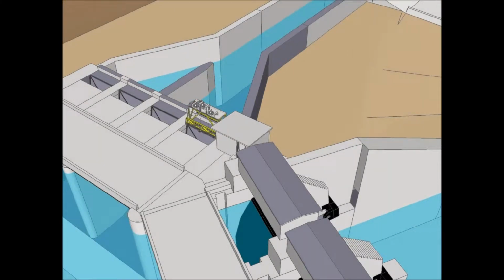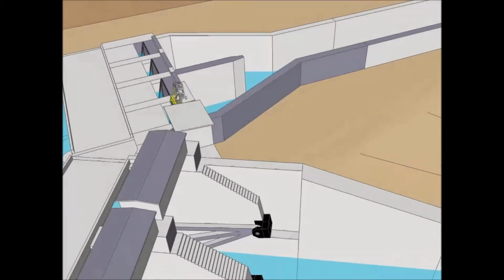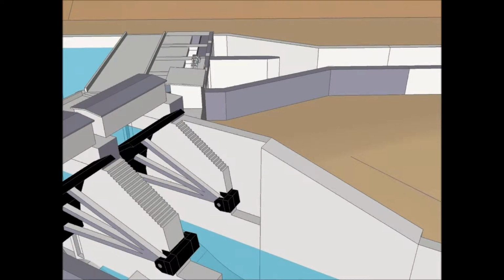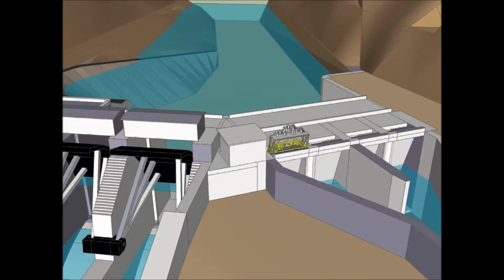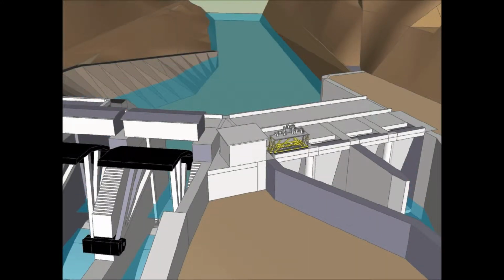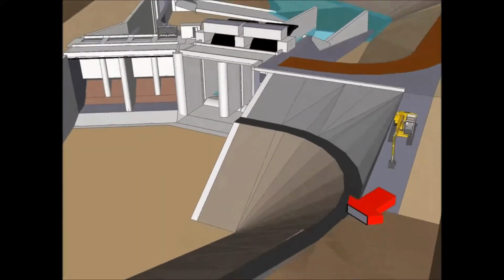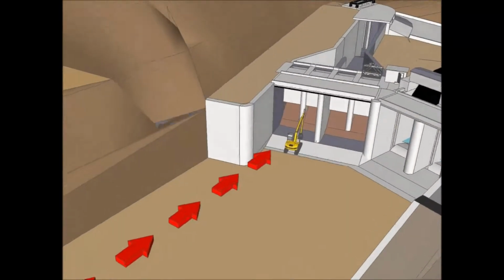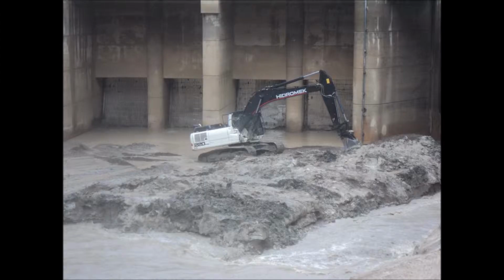So here's our current response. When the water level on the tunnel side of that intake channel reaches a predetermined point, where we've determined the generation losses are unacceptable, the decision is made to schedule an outage to go in and maintain the trash racks. So the radial gates are open as we see here, and then the weir basin is emptied. Once the conditions are safe, a working machine actually drives down through the riverbed to reach the front of the trash racks. Now here are a few pictures of the machines in action, and you can see them actually driving right up the middle of the riverbed.